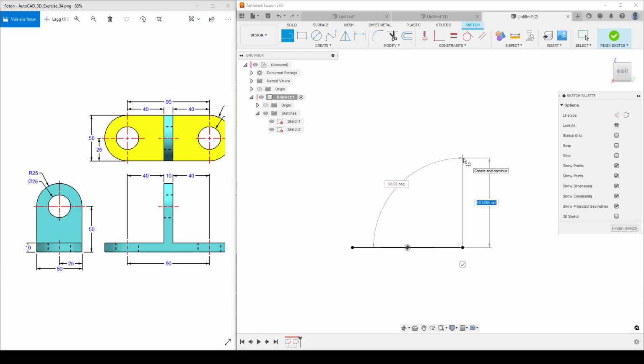So just use that, move it up, hold down the mouse button, and we can do the arc. But I will not just randomly release it here. I will move it down to this point down here. Move it straight up. You see I get a small helping line. Keep on moving until it pops up. You can see it slightly locks in place here. So if I release there and then go straight down to here, I get the tangent constraints and things get